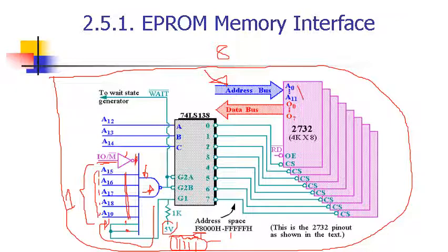So now they are all used to decode a single low bit used to activate this decoder. So they provide zeros for your G2A and G2B, while this source is providing a high voltage to G1. So now we make sure that your line decoder is active.